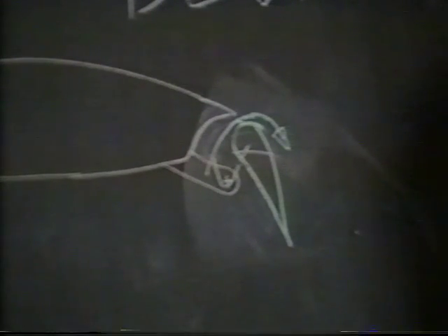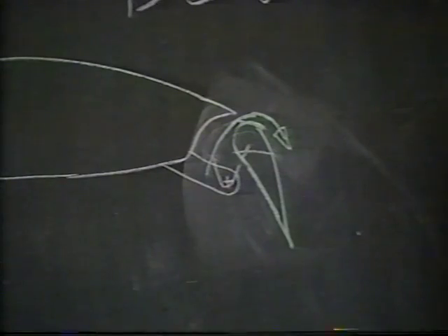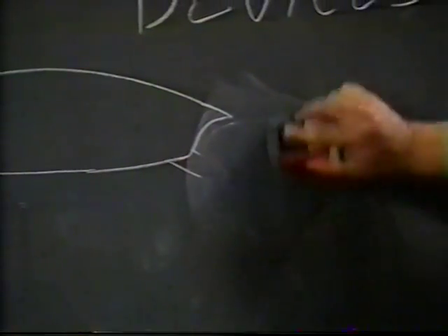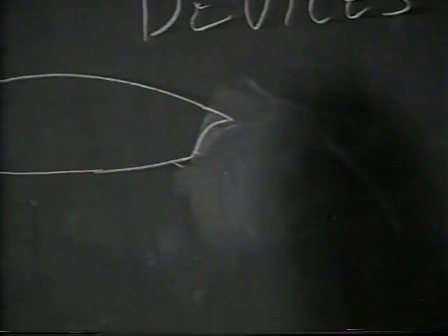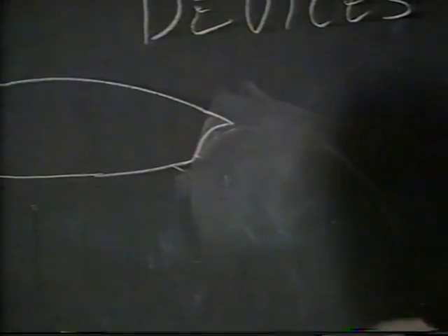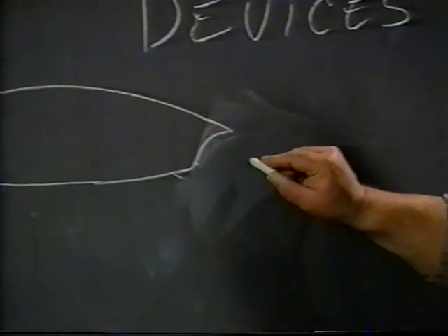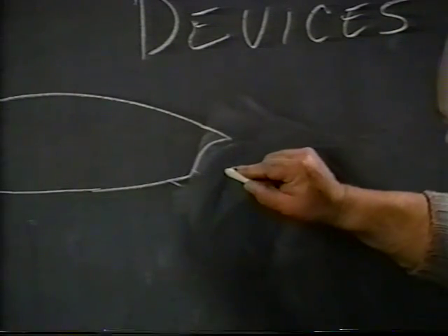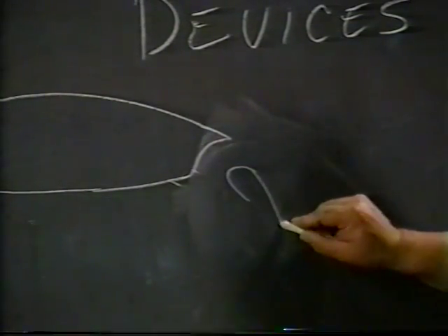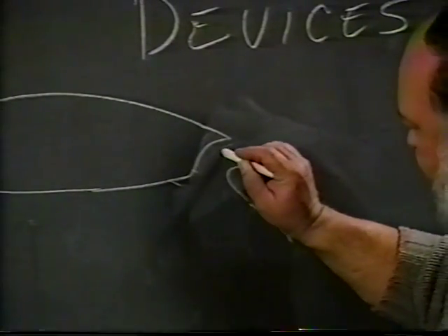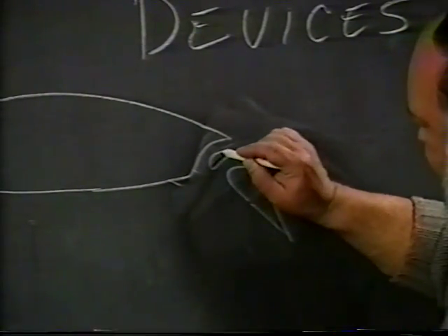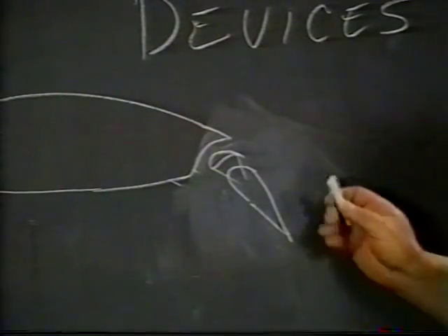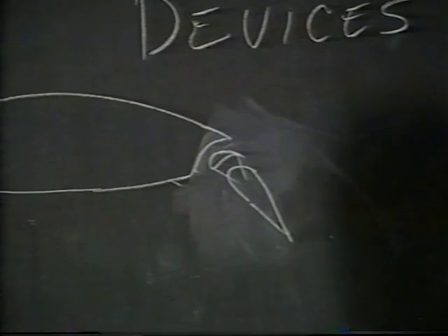The one that we have that would be better than this would be a double slotted flap. And really, what that comes out to be is something very, very similar to the single slotted flap, except that the flap itself, and I'm just going to draw this flap now in the down position, has two slots essentially in it. First, you've got the flap section itself, and then a little auxiliary airfoil built into it. This is connected directly to the flap itself. The two units work as a unit.